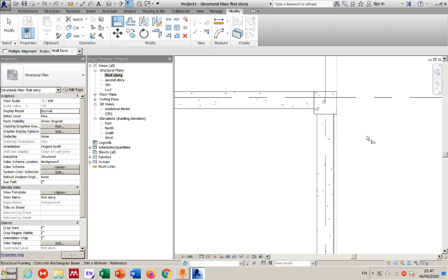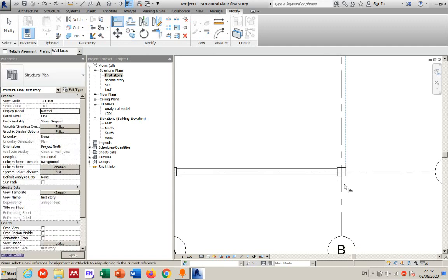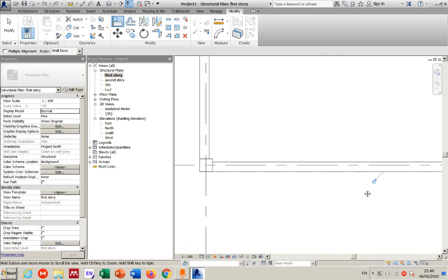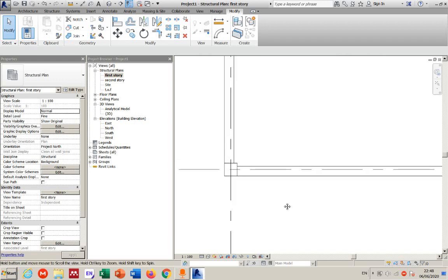It's easier than move, but not always working. It needs a face to work with. You can just simply click the face, and you click on the second one. It's going to be moved, aligned. The name of it is aligned to this face there. It's easier than move, but remember, move is sometimes useful for the purpose when align does not work. If align cannot find the surface, it will go in this manner.